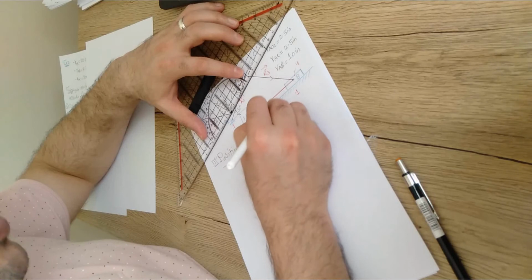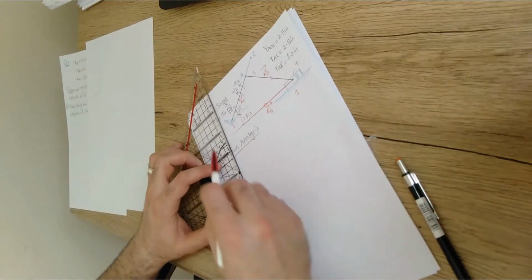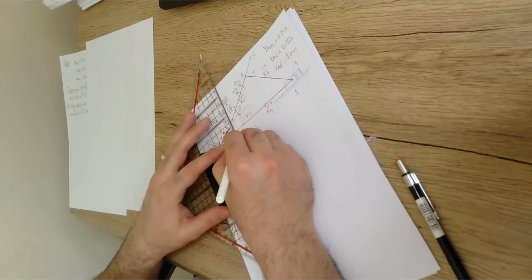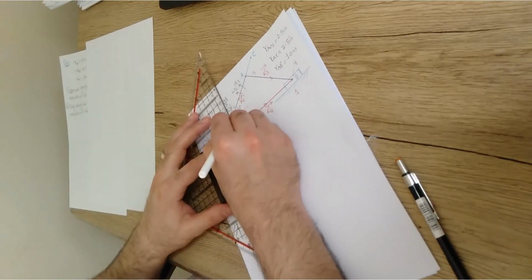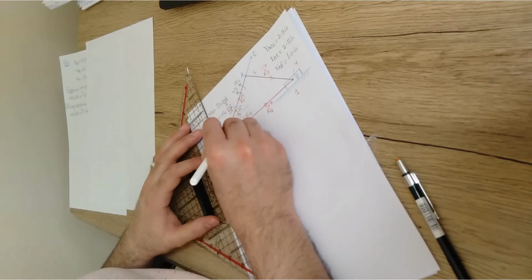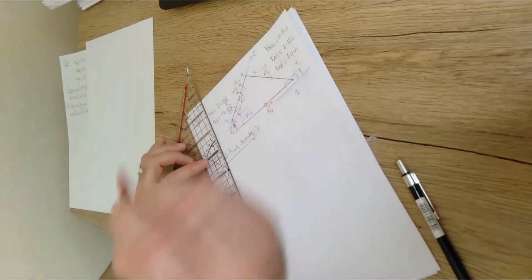So it means that there should be an R4 vector, and this R4 is working for the slider itself. As you can see, we end up with a loop, but this loop is open. So we have to close the loop with an additional position vector that we are going to set up here as the R1 vector, which should be the ground.